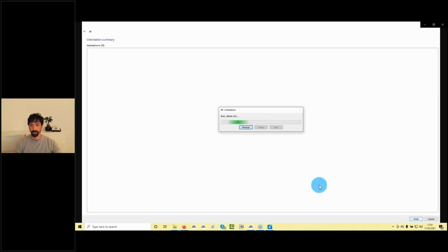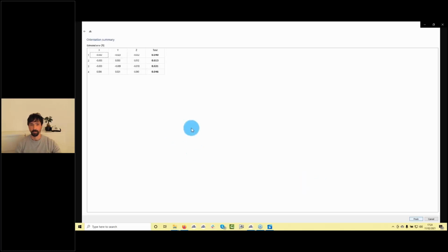Maybe just in the meantime, if you don't have a Phantom 4 RTK or Matrice 300 with an RTK on it, we always advise to use a minimum of 3 GCP points per project. But to have good control over it, it's great to have 10 ground control points per battery. So you can cover this area and get really great results already, and it's super fast altogether.